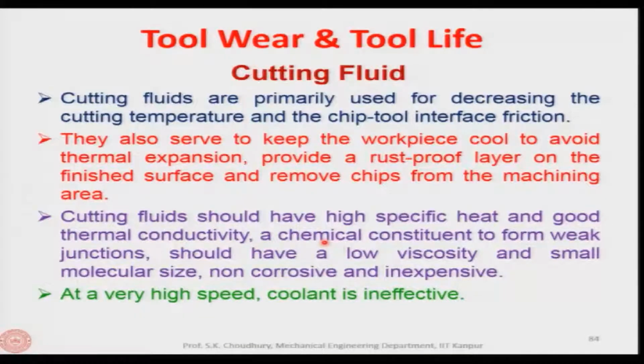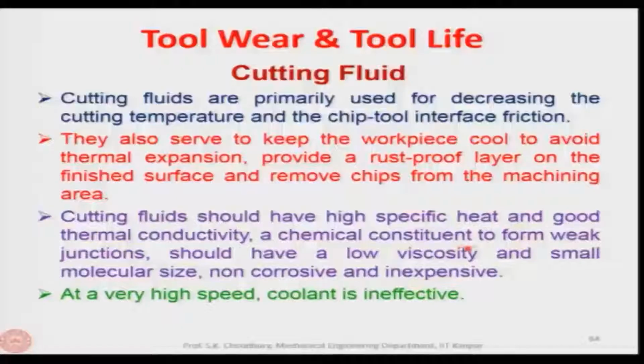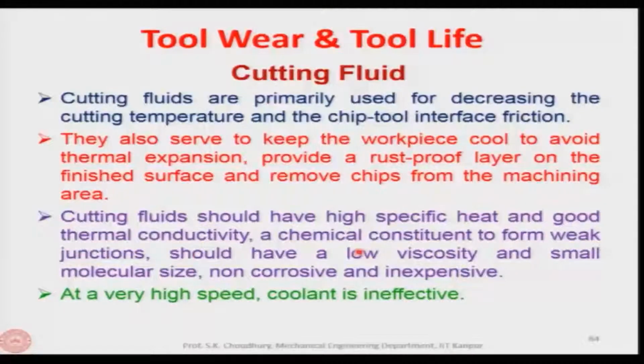Cutting fluid should have high specific heat and good thermal conductivity. This is also understood, so that it actually takes out the heat from the machining zone. It should have a chemical constituent to form weak junctions, so that built up edge does not happen, because built up edge happens because of the nascent surfaces. If the nascent surfaces are covered with a layer, they cannot get welded, and therefore, there is no built up edge formation. So, this is the mechanism. It should have a low viscosity, because it has to penetrate. If it is very thick, very high viscosity, in that case it cannot penetrate the machining zone, and it should have small molecular size, so that it can penetrate easily, be non-corrosive and inexpensive.